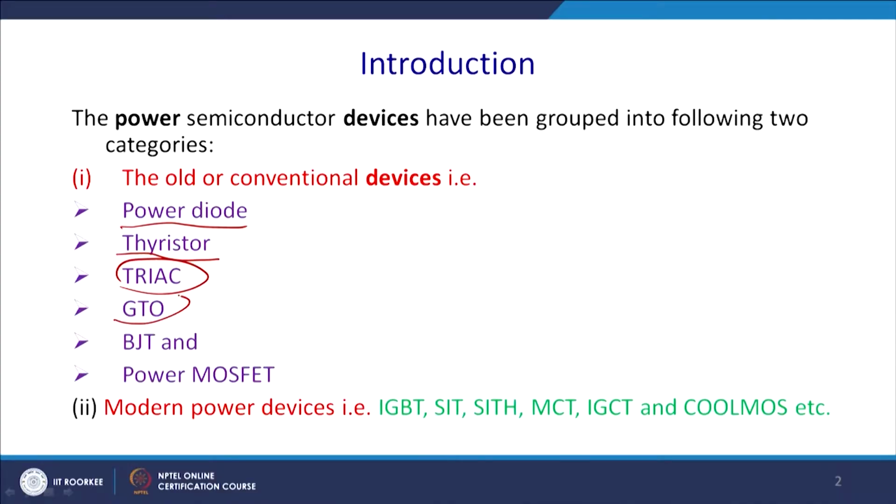Thereafter the GTO. Since a thyristor does not have a turn off capability, it requires an external procedure to turn off, called commutation, and we can turn off a kind of thyristor with negative gate current. So, that will be the GTO, which will also be covered.